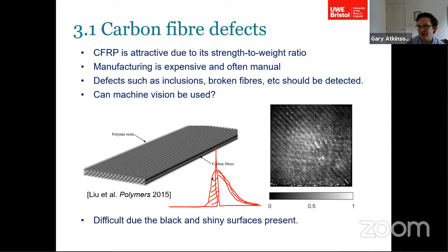So there's pretty much no way that I can think of that you could use this to look for subsurface defects. If you wanted to do that, you would need to use things like ultrasound, like a CT scan. Having said that, one of the applications of this is not necessarily as a post-manufacture inspection, because obviously, if you've got a void or delamination, that will be a major thing that you're missing if you don't detect something like that.